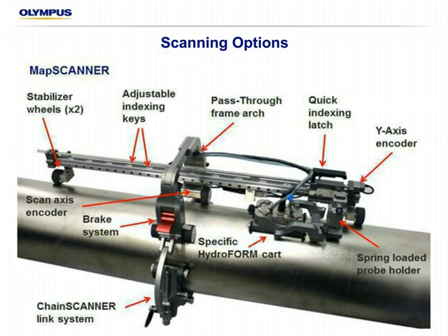We would scan all the way around once around the pipe, and then these quick indexes are actually set to our preset value of how far we want to move on each index. We just click it over to the next one, scan again. So it's a very rapid, very optimized thing, but you're still having an operator do this scan, with the benefit being a lower cost solution with no automation, but you get full encoding in both X and Y axis.